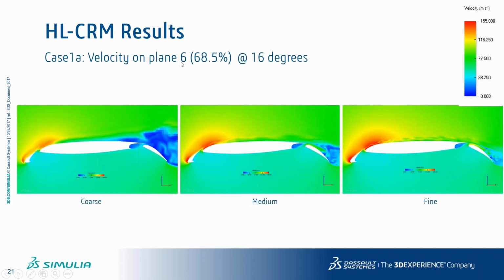When you take a cutting plane at plane 6, which was approximately where the separation occurred on the previous slide, for the coarse case you can see it clearly. Okay, maybe you can see the voxelization, it's squared on the lattice. It allows us to appreciate the lattice size we use for the simulation, which is pretty coarse. Okay, and we can guess that the size of the cubes here is probably too coarse in this region, in this gap here as well, which means you've got a continuous blade element almost. It doesn't discretize the gap here and the flow cannot flow out from there.